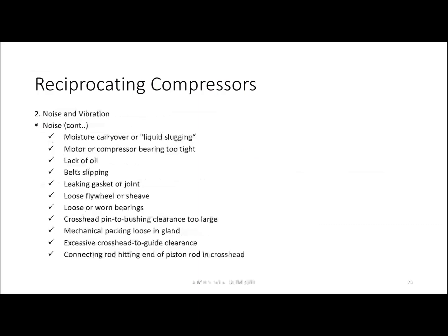It can also come from a leaking gasket or joint, loose flywheel, loose bearings, crosshead pin to bushing clearance too high, mechanical packing loose in the glands, excessive crosshead to guide clearance, and the connecting rod hitting the end of the piston rod in the crosshead. Maybe some of you are not familiar with these components of a compressor, but because you are mechanical technologists, I hope you can read about what is inside a compressor later, right?